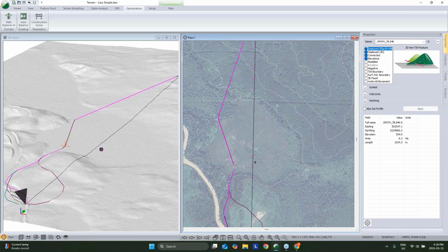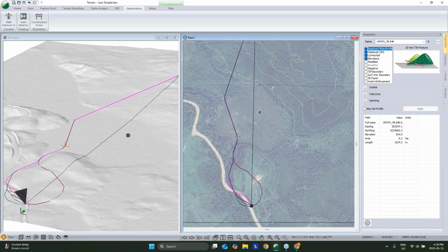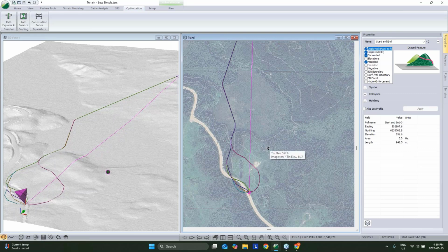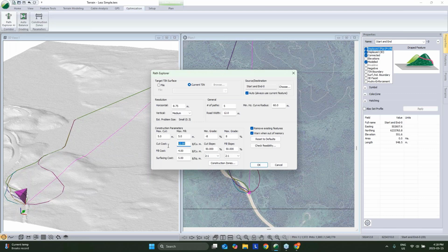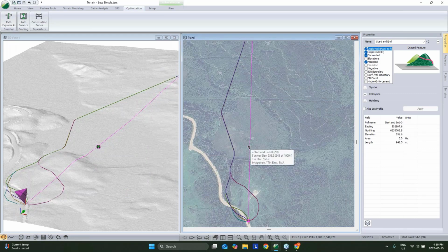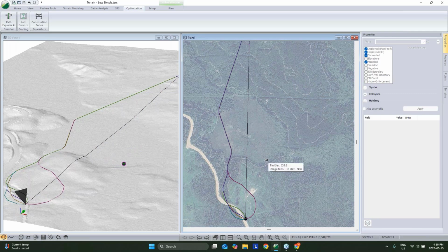We're going right across to what's most likely a bog, and then we're crossing and going across it again. So as the software searches through for the best place to put the road, it's looking at that trapezoidal cross section, looking at our cuts and fills, but it's not really differentiating the ground types or anything like that to be different. That's up to us to tell the software what to consider.